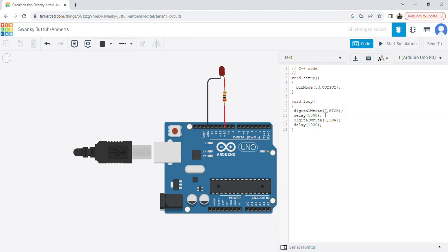That's it. Okay, so again you connect this now, change the number, change this pin number 7 to 10. Okay, so this is the very simple code. Now we know that I am setting the pin number 10 as the output, and this I am doing one time, so I am writing that particular command in the setup part. The command for this is pinMode.